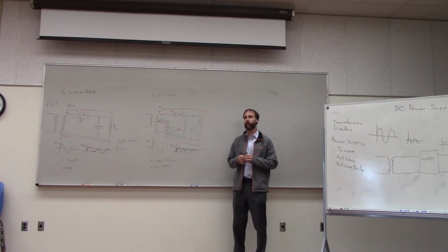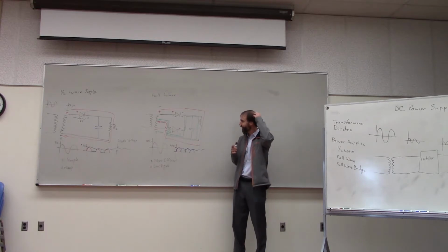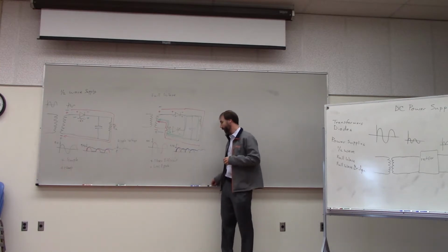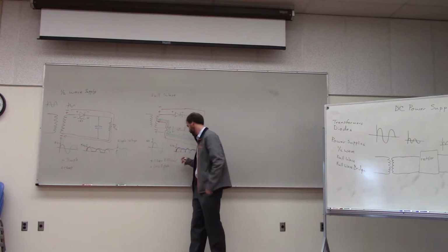Real quick, does that essentially double the frequency? Yes. So if you had 60 hertz, it'd be 120? Exactly. That's exactly right. What do they use this type of power supply for? Well, so we'll get there in a second. Advantage is that it cuts the voltage in half. Yeah, exactly. So that's definitely a drawback.